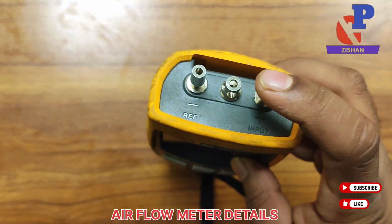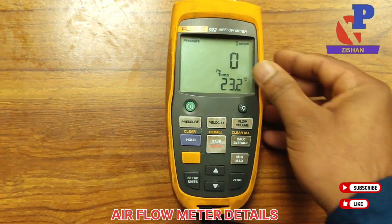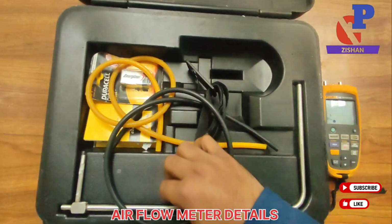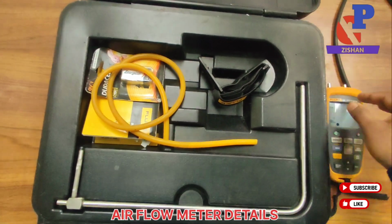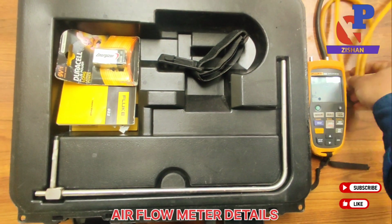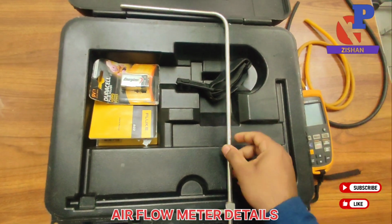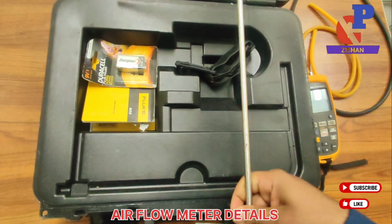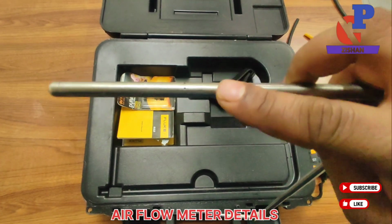From the top side there are two pressure hoses, one is the positive pressure hose and another is the negative pressure hose, and the third one in the middle is a temperature sensor. This takes the area temperature, not the temperature inside the duct. The two pressure hoses are yellow and black. The yellow one we connect to the positive pressure side, and the black one to the negative side. For the velocities and flow volume we require the static pitot tube.